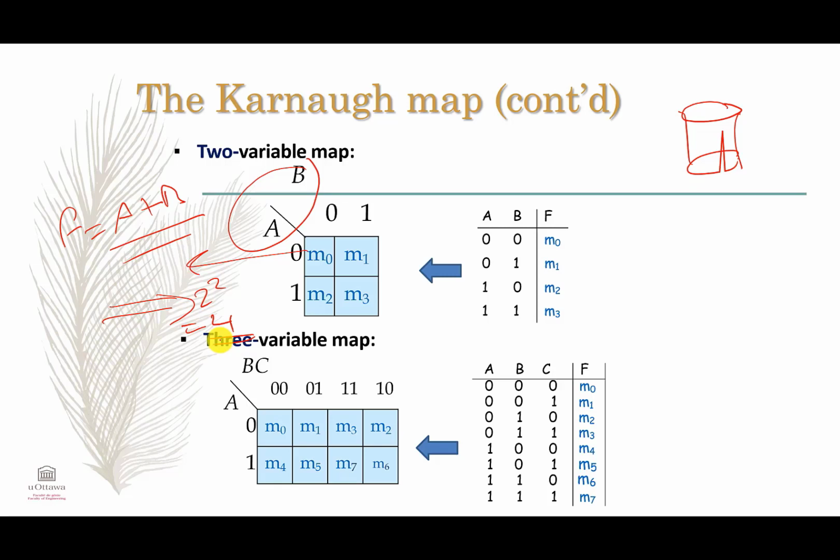Now you have to understand, guys, that the Karnaugh map is just a reproduction of the truth table in a graphical way. Basically, that truth table can be rewritten by indicating A to be the index of the rows and B to be the index of the columns. So here we have 0, 0, that is 0 and 0, therefore we put the value here of 0 and 0 from our truth table, which here we indicate by M0.